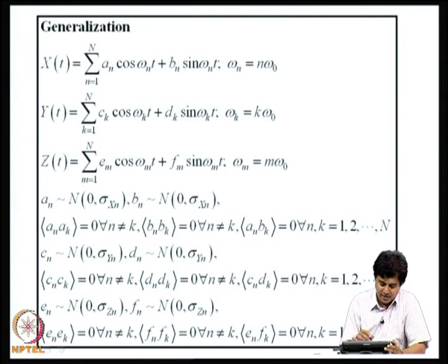So, each one is a stationary random process. Finding the properties of an and bn is purely based on the property of PSDs of x, y and z, for say an, bn, ck, dk, em, fm. But to find the cross properties between an, cn, an, en, etc., you have to bank on the cross power spectral density functions.